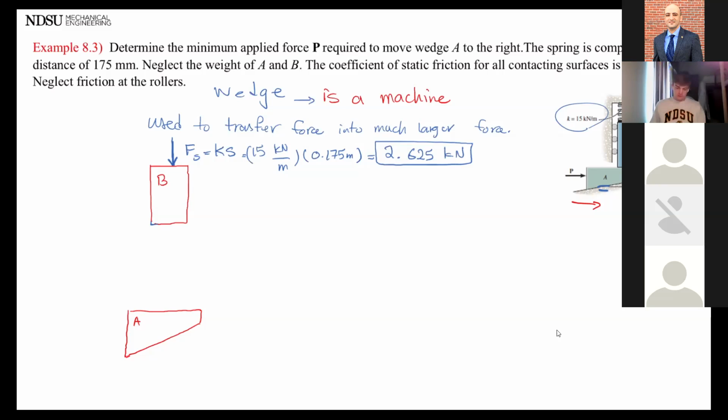What about reactive forces? You have your normal force. Okay, where? At the bottom, going the opposite of the spring force. Okay, normal force perpendicular to the surface. All right, great. As soon as you draw a normal force, draw a friction force tangent to the surface. Now, $1 million question: is the friction going to 1 or is it going to 2?